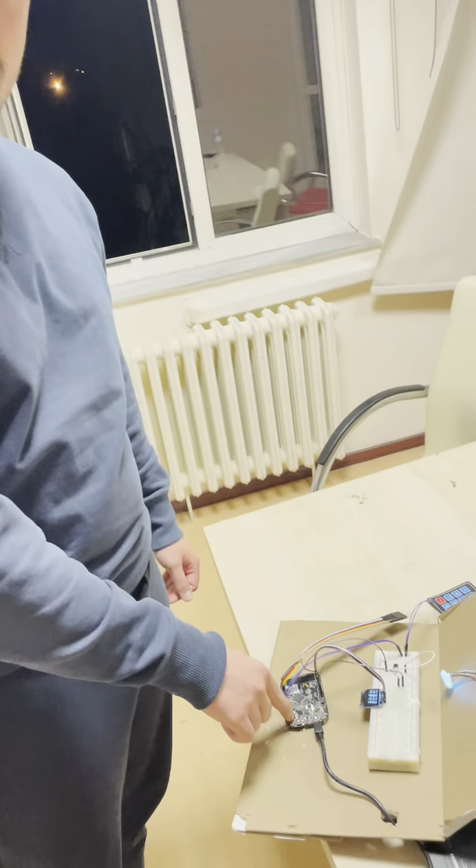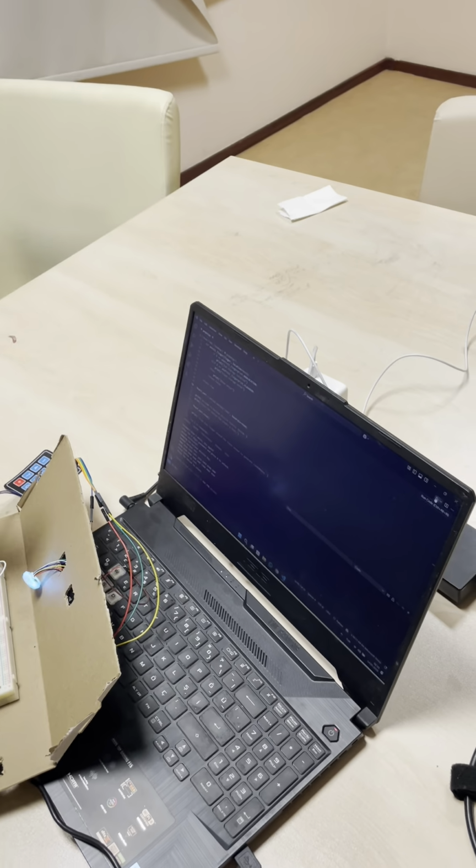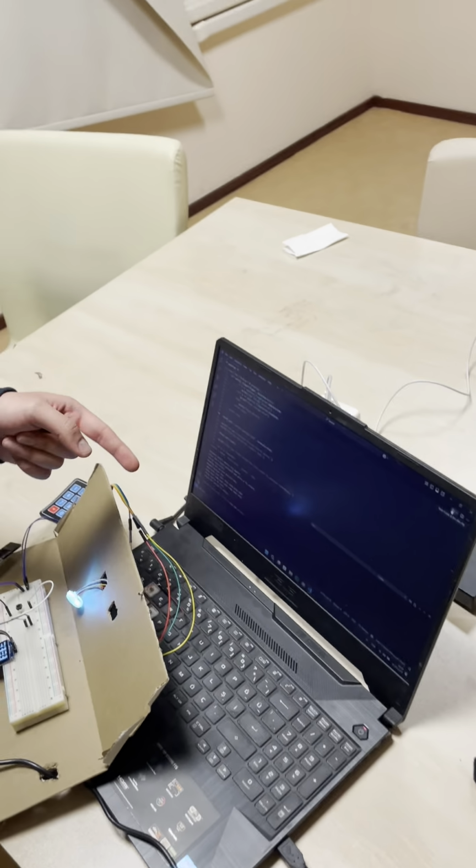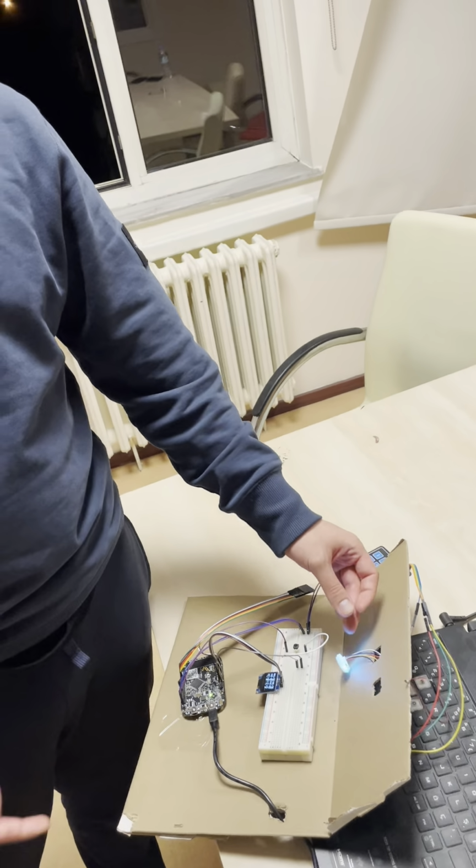And also there are two code sections. One of them is the C part. Actually, the main logic was written in C on ARM and it is embedded to this freedom board device. And there is also a Python code for the user interface. There is UART and I2C in my project. UART is used for the communication between the Python part and C part, and I2C was used to communicate between this fingerprint sensor and C code.